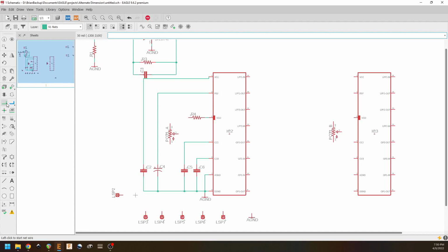And let's see, we'll actually wire this guy up. So this potentiometer is going to be wired up as a variable resistor, which means that the wiper lug is going to be connected to one of our two outer lugs. And because we want this to be a higher resistance as lug 2 turns all the way clockwise, that means what we want is lug 2 to be connected to lug 1 because, oh, nope, let's see.